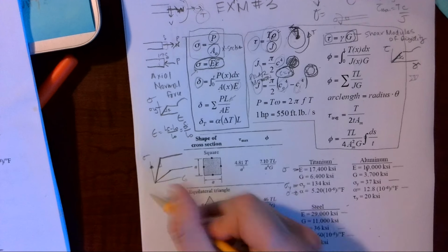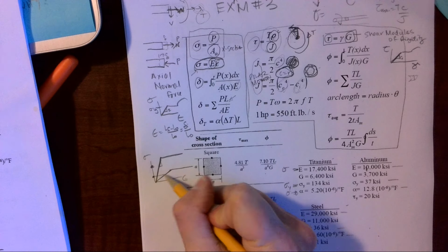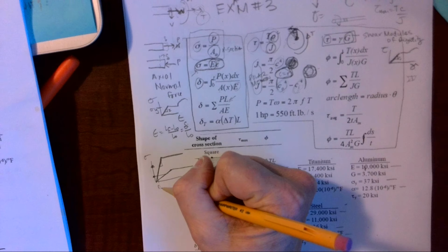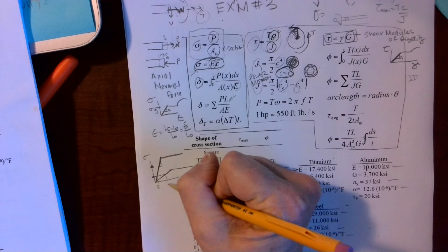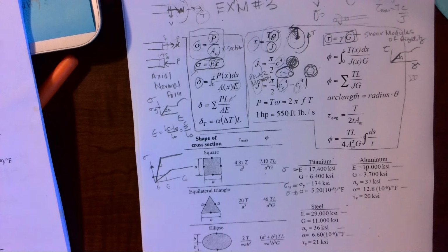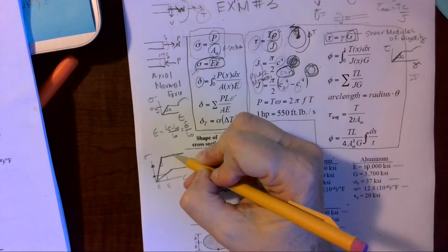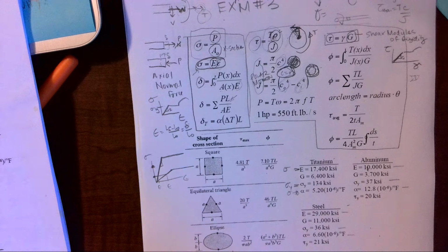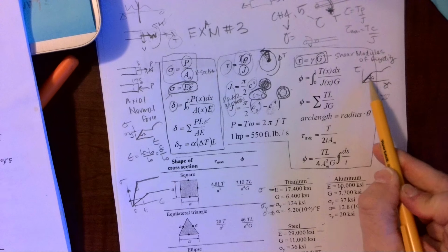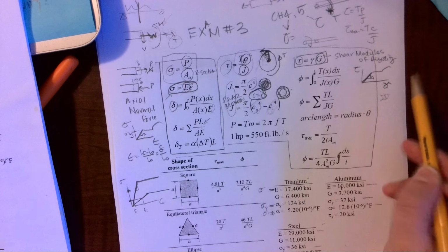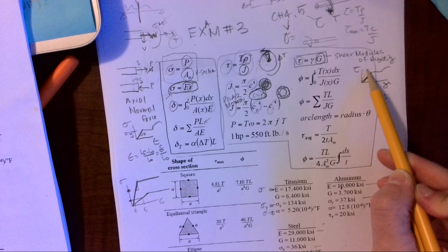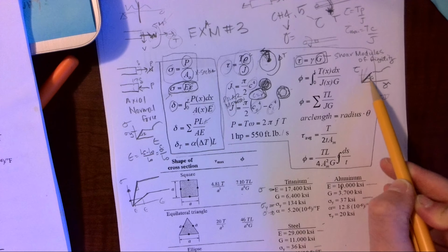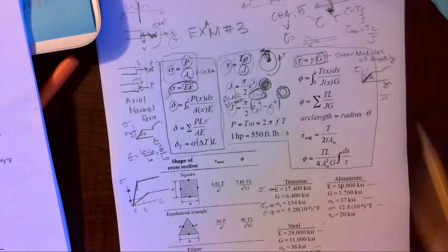When I look at this point of stress, I can see for my steel, I might have a very, very small strain, but for my rubber band, it's ginormous, okay? So this might be steel, this might be rubber band. They'd probably look a whole lot different than that, but it gives you the right idea. So the same holds true for here. If I have two materials with a different modulus of rigidity, I can have the same stress, but I'll have a different amount of shear strain, okay?